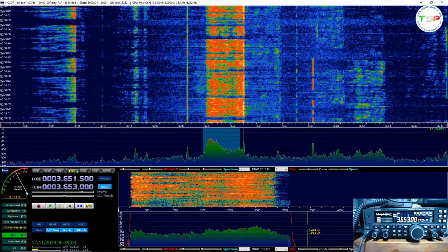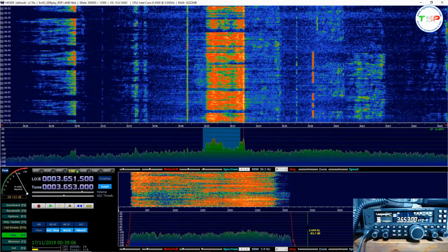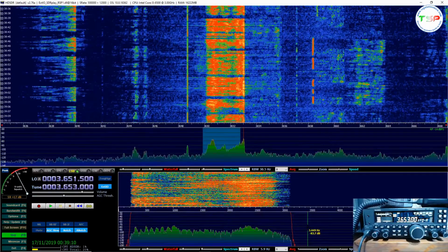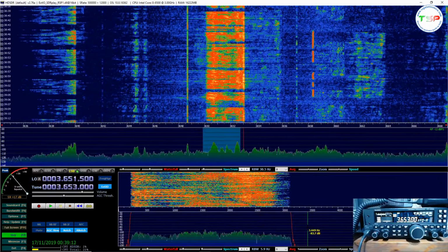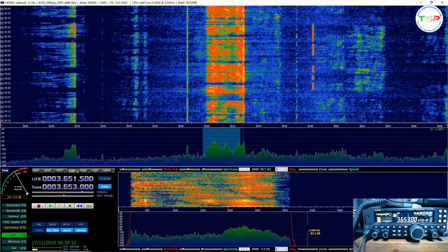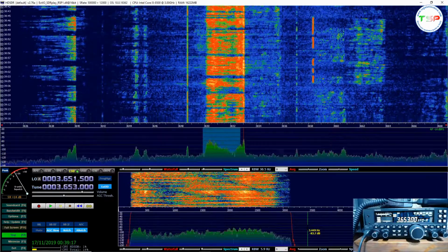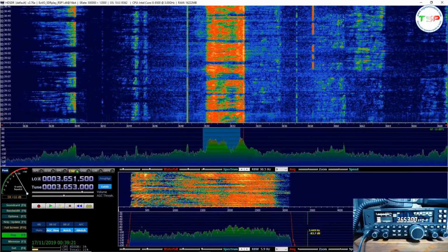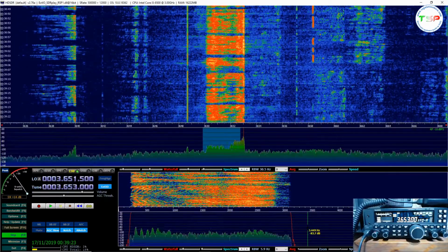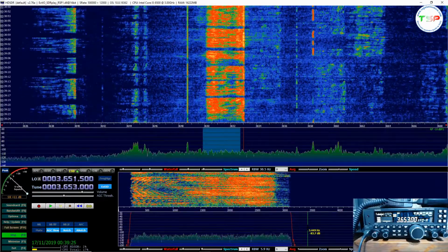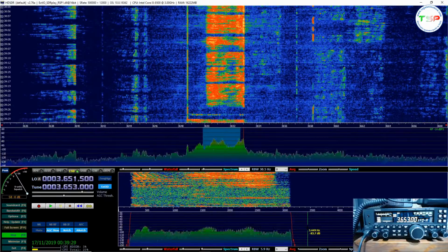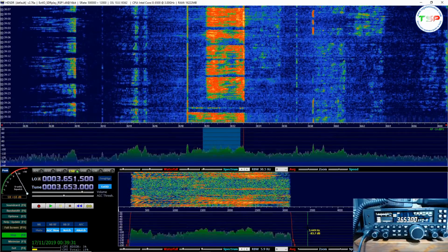So even with those USB dongles that are very cheap, you can have a good reception. Now I'm using the SDRplay RSP1 because it has a higher resolution, more bits. Instead of 8 bit, it uses 12 or 14 bit per sample, and the reception is a little bit better, with less noise. Okay.